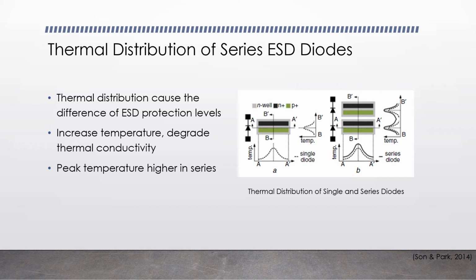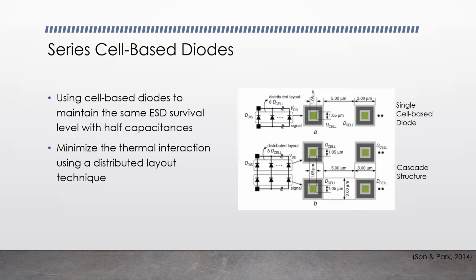So in reality, the level of ESD protection of series diodes is lower than that of single diodes, but with smaller equivalent parasitic capacitance.